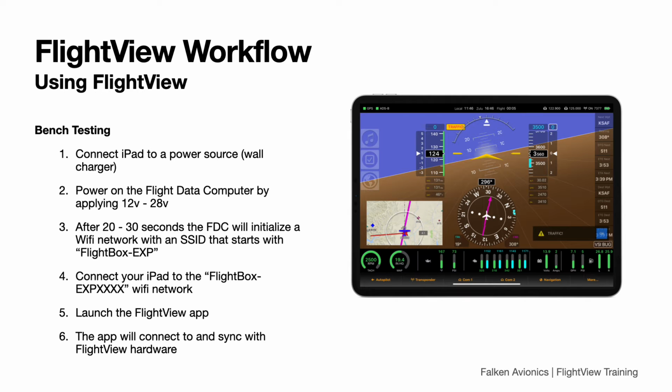To be able to configure back-end services, you'll want to connect the peripherals, the GPS receiver, air data computer, and engine monitor, to the FDC and power them up. The flight data computer and the engine monitor both require a power source. You can use either a 12-volt or a 28-volt source. A standard off-the-shelf 12-volt transformer capable of producing at least 1 amp of power should work.